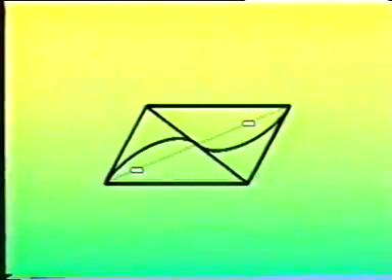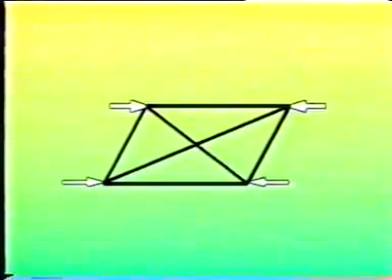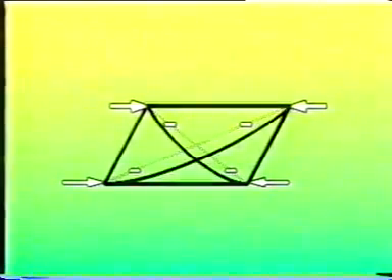The great slenderness makes this member buckle easily, and a statically determinate system is left. Obviously, it is not allowed to place this bracing in a position above the neutral axis of the main girder, unless the members are designed to carry compressive forces.